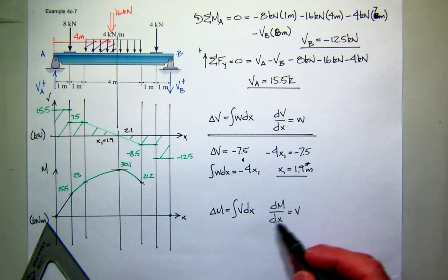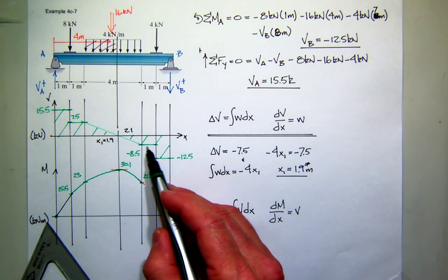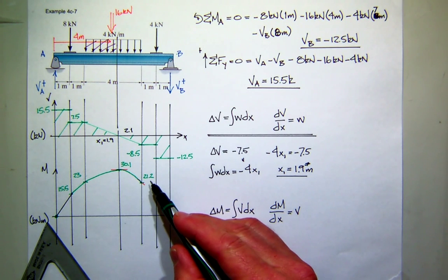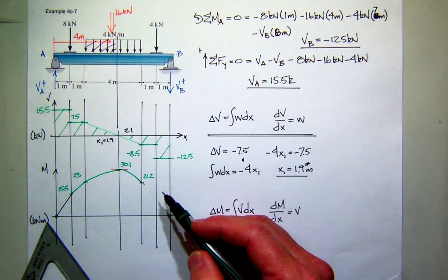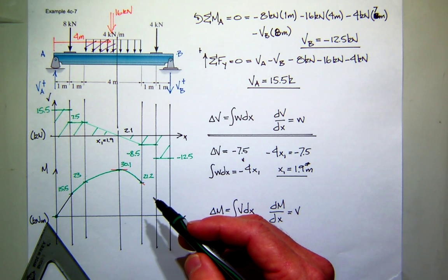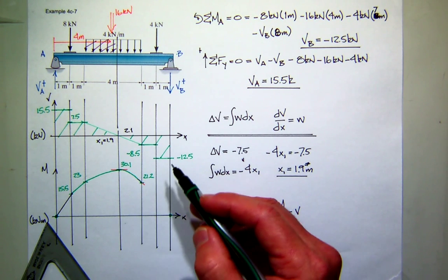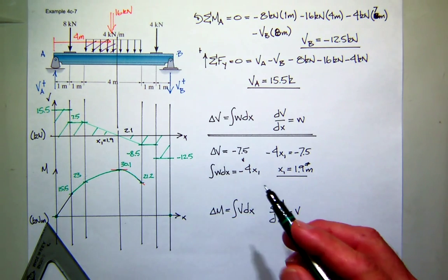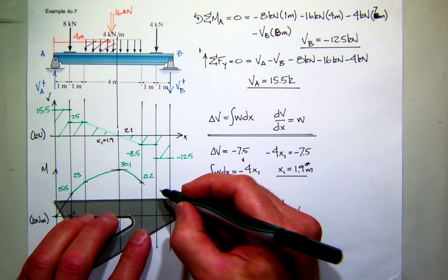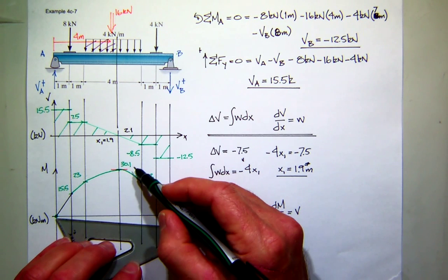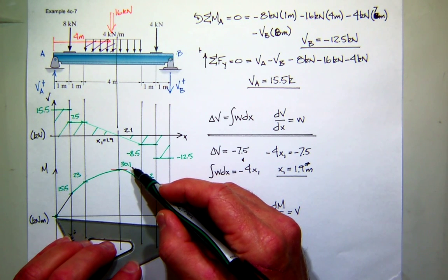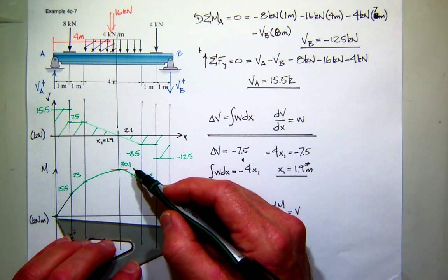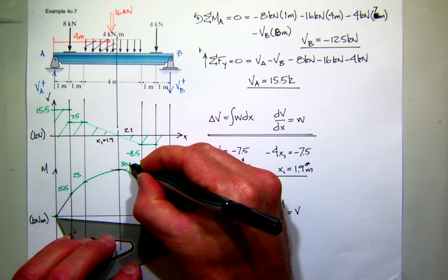Now what's the change in moment over this next meter? Negative 8.5. So subtract 8.5 from that, and what do you get? Do we get 12.5? We're going to be off a little bit, aren't we? What did you get? 12.7. Somehow we lost something along the way. Well, the 30.1 is supposed to be like 30.0. Yeah, I used the actual numbers as opposed to rounding each time. 30.03. So this is really 30.